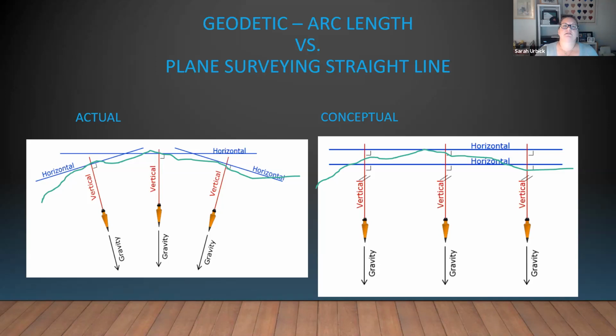So that homework problem where you were given the circle, you had an arc length, you had points A and B, and we had to find the length in between them. We might need to find that arc length if we're doing a geodetic survey, or if we're doing more of a tangential point and looking at just that length across, figuring that the height difference is going to be negligible. We're creating enough of a flat plane that we don't have to account for that difference.